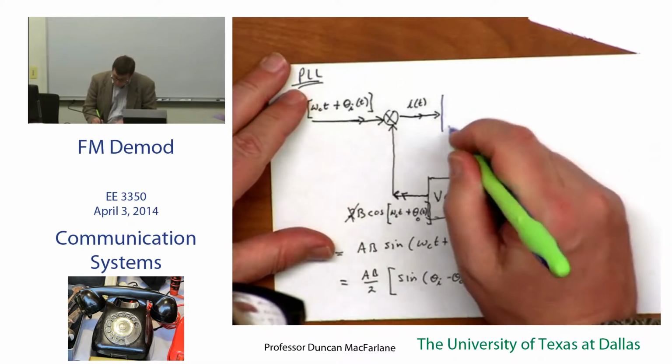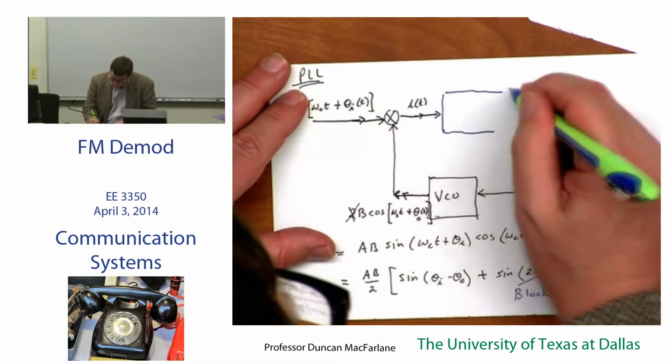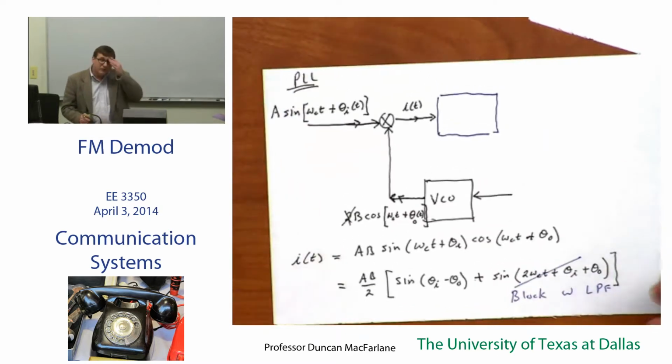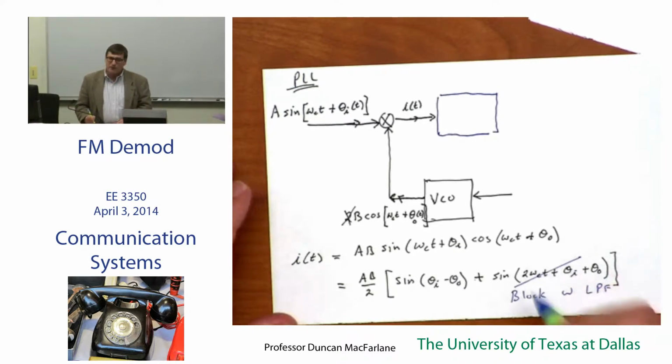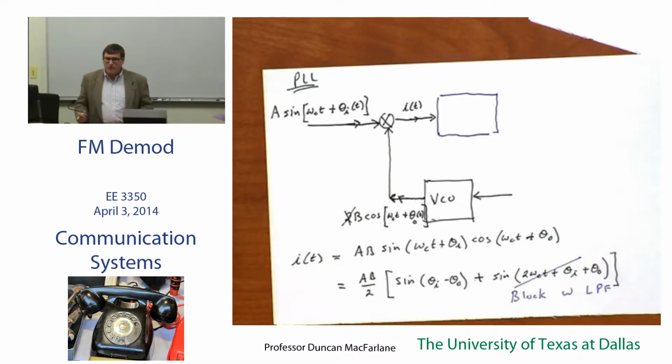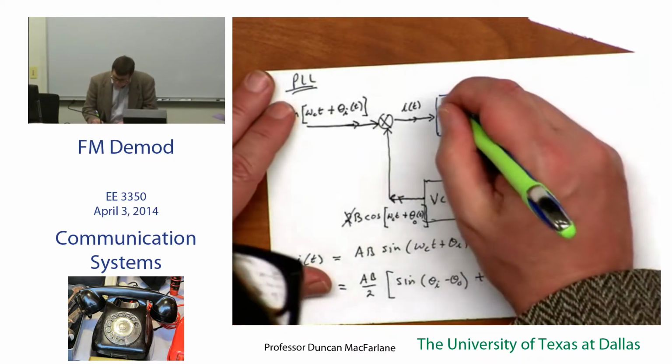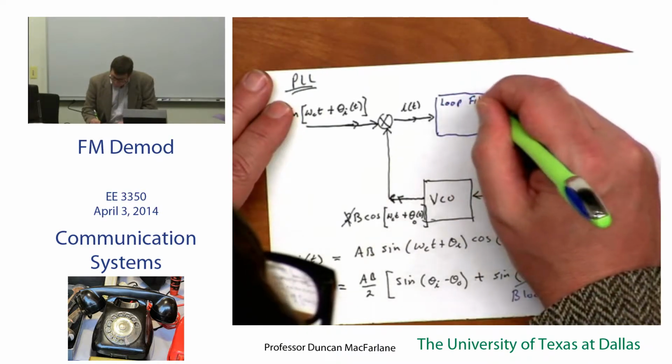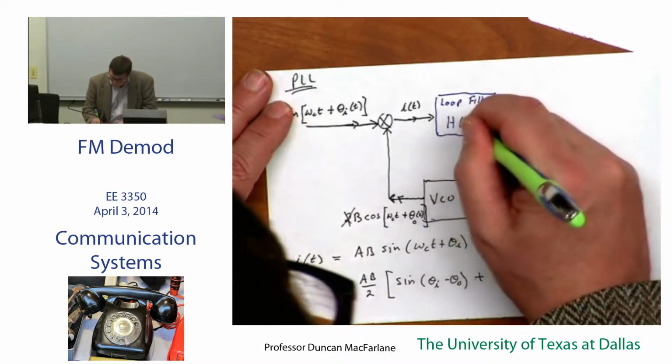And so what I'll do, and I'll be a little bit general. Okay? We can say I want a low-pass filter, and we do want a low-pass filter. Okay? But the art sometimes in doing these kinds of derivations and these design explorations is you might as well load in a little bit of extra degrees of freedom to take care of the things like the low-pass filter that you know you want, but also to give you some wiggle room to sort of do other things that may be good or may be bad or may be neutral, but you'll find out about them. And so what we'll do is we'll put in a generalized loop filter with a response H of omega.